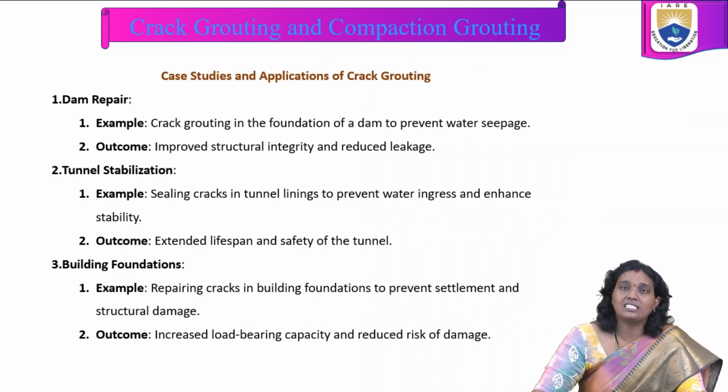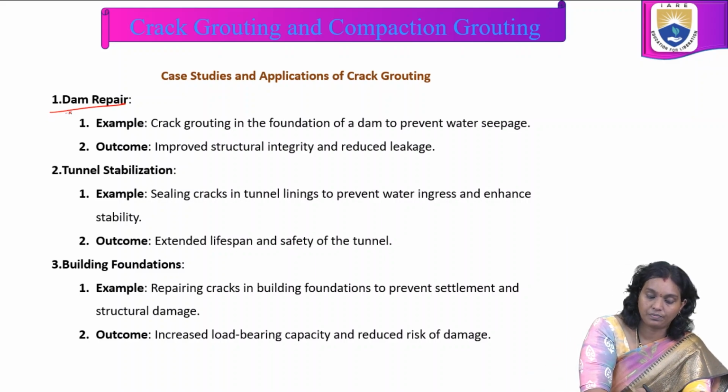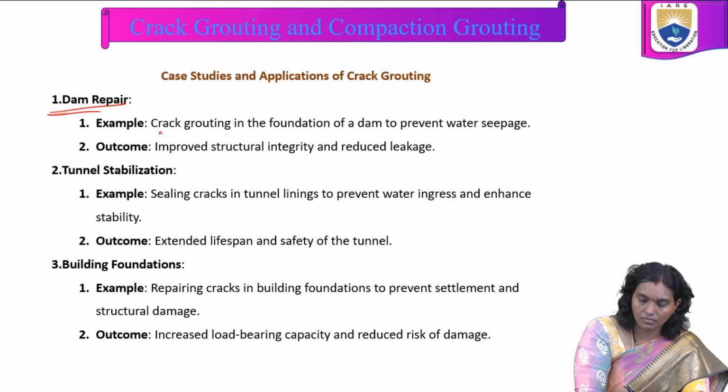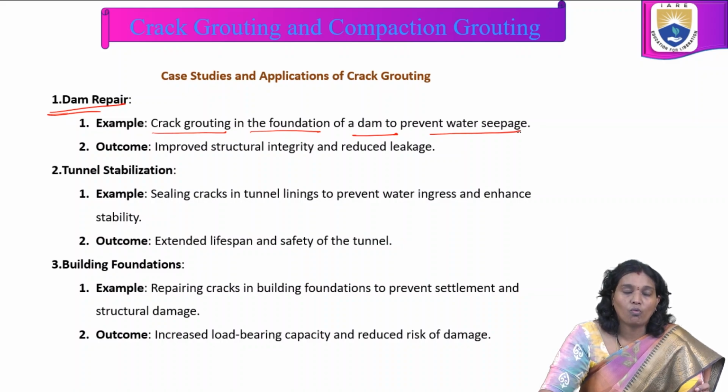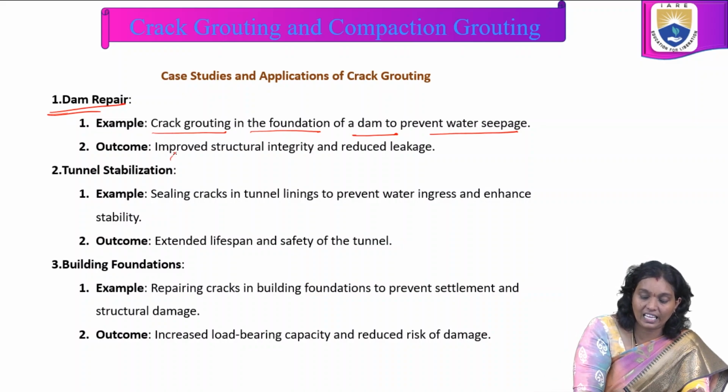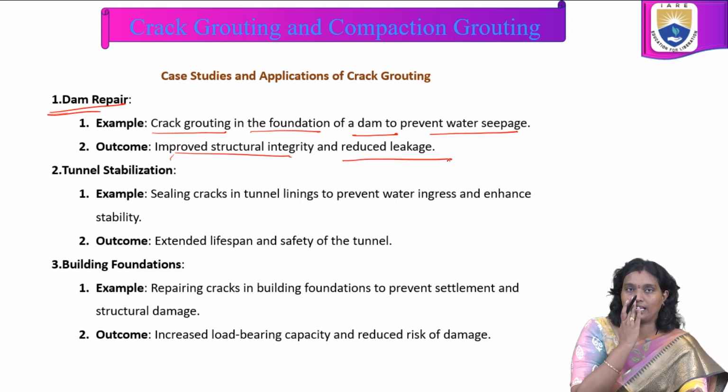Some of the case studies and applications of crack grouting. Dam repair. Example, crack grouting in the foundation of a dam to prevent water seepage. So, what is the outcome when we apply this crack grouting? The outcome is improved structural integrity and also reduced leakage.